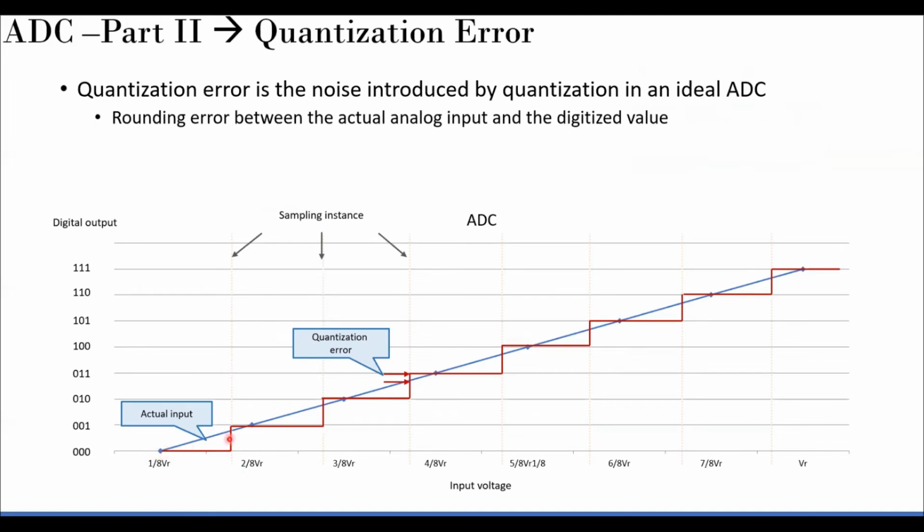Okay, so once you select the range, this is how the quantization, or the sampling in amplitude, happens. I'm showing a blue signal, which is an analog ramp, increasing, and on the y-axis I'm showing the level. Sorry, here it's a 3-bit case. So 2 raised to 3, 8 levels, 0 to 8, as you can see over here.